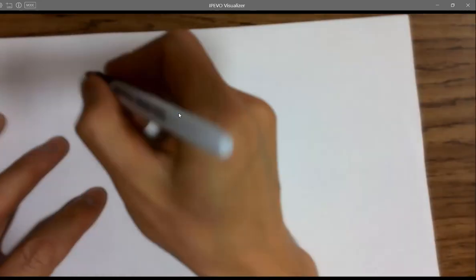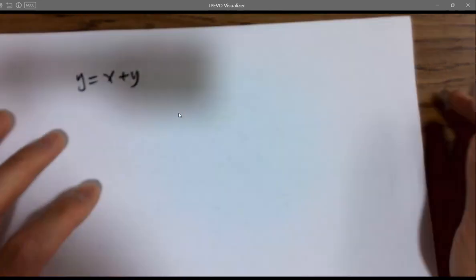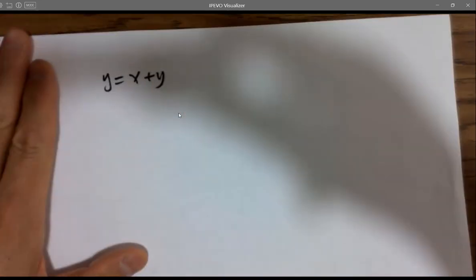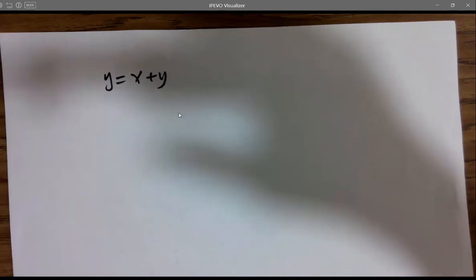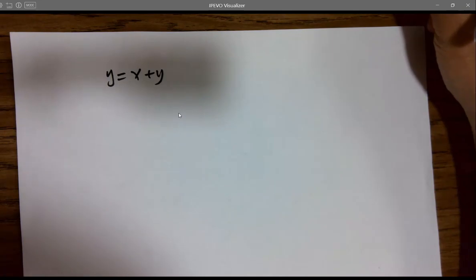So in C++, you can directly put, for example, y equals x plus y. That's C++, right? But in Verilog, you are not allowed to do that. You are programming a circuit instead of a calculation or operation. Even though it looks very similar to C++, it's not C++.